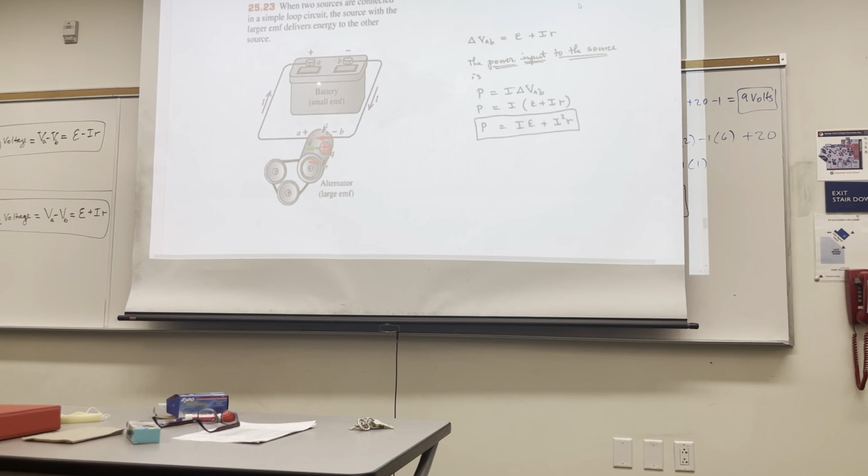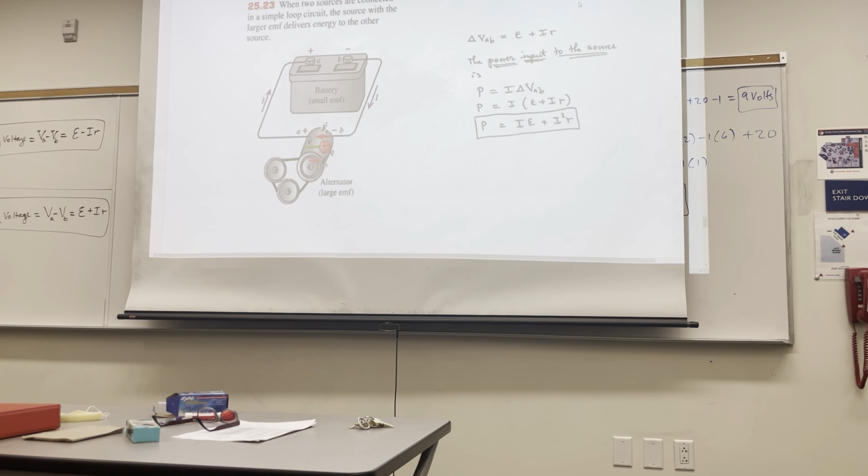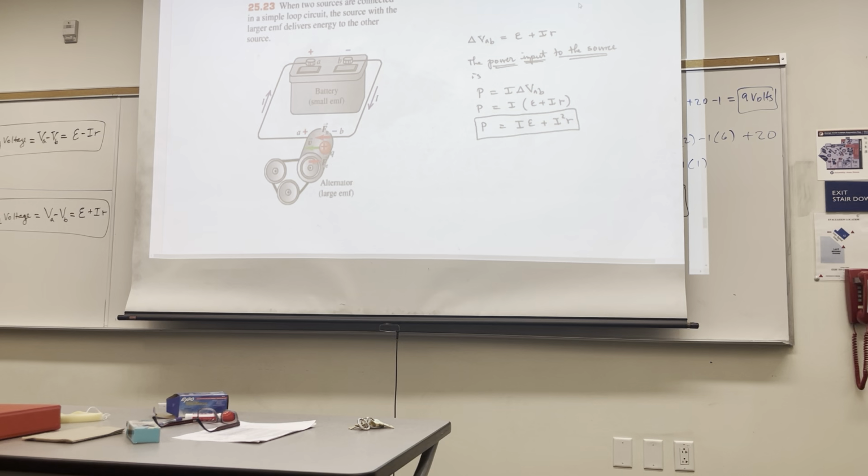Now you have the battery in the car, but now we have an alternator here that's actually used to charge the battery, to keep the battery from draining. Right? And so notice that now the battery is getting charged by the alternator, and now notice the direction of the current into the battery. It's coming in at the positive terminal. This battery is getting charged.